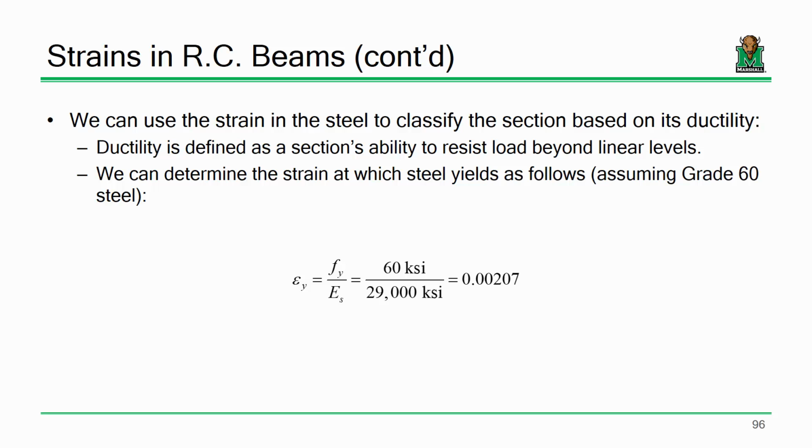Okay, so let's say we've got our stress-strain curve for steel. You make do. Oh, wait, I got a marker. So sorry, YouTube. Okay, so here's my strain, here's my stress. If we're just zoomed into the linear range, steel has a behavior that's linear, and then it yields.